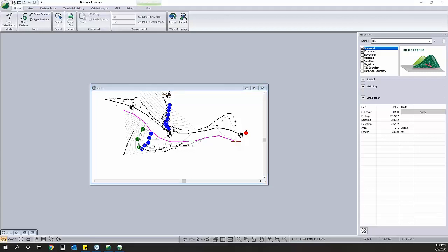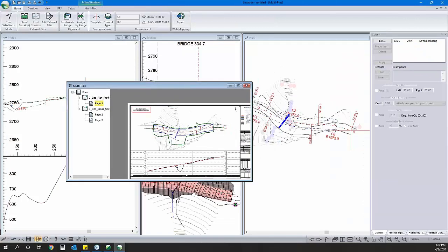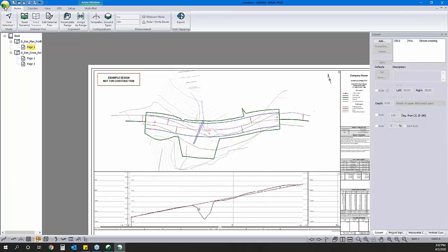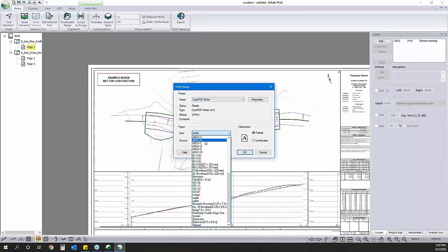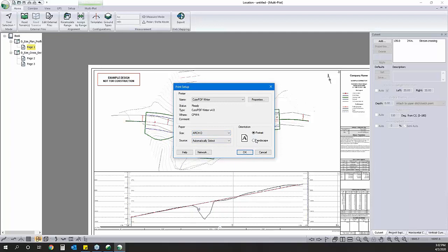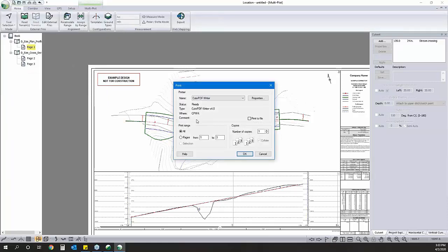Is it possible to export the design to a PDF document? Yeah, so we've got that. I'm going to go printer setup. So my printer is set to be a PDF writer, so it's just the same as printing it. I'm going to set my sheet to be RHD, so that matches the design, the formatted drawing size, set my landscape, and hit File, Print, and that'll just save wherever I decide to save it.